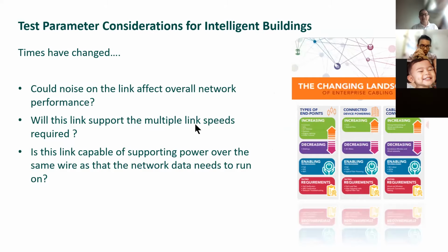So again, this is just an overview to show you how important the physical cable is. It's not just testing the signal, but also whether your cable can deliver 100% without any issue, without any noise interference, or with minimized losses along your cable. And is your cable able to support power, PoE?